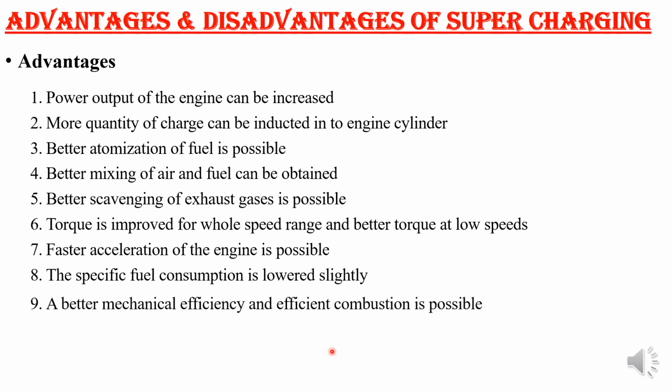Then better mechanical efficiency, obviously, because power output is going to increase, BP going to increase, hence mechanical efficiency has to increase, and efficient combustion is possible. Then the tenth one is, in a CI engine, exhaust smoke can be reduced. Smoke can be reduced. So this is another advantage. So these are the advantages of supercharging.